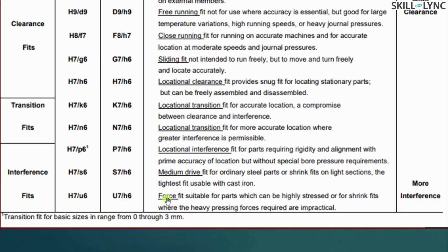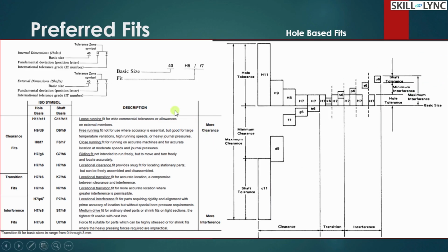that is the force fit. It means that you either heat it or shrink it, or exert heavy stress, that is, you hammer that element into the component. That means that heavy pressing forces are required to do it. So in these conditions, though they are two different components, after fitting they are going to behave like an individual single component. So this is how you select the different fits that you require based